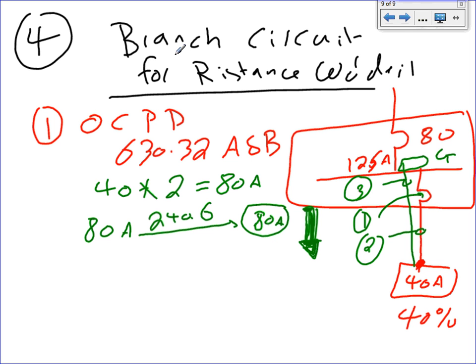I can put my overcurrent protection device at 300% right here, or right here, mostly right here. But then you have to up your conductor size. Sure, but I guess Mike Holt breaks it down a little differently. He says each welder must have an OCPD of not more than 300. So would it make sense just to go 300 from the start? Yes. Then your conductor has to be sized for 300. You can absolutely.